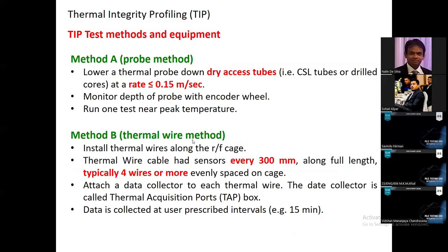Okay. So two methods are available, as I said earlier. Method A is available in Sri Lanka. It's less expensive. We can make use of cross-hole sonic logging tubes, or you may have to drill if you are planning to use method A. This test is conducted when the tubes are dry. You can't have water in the access tubes, right? So you must remove water before conducting this test.